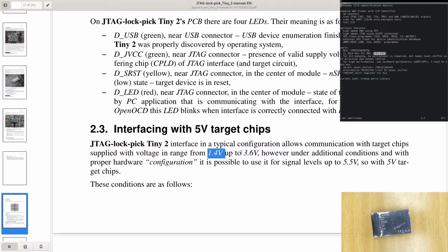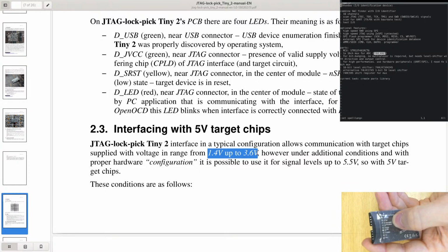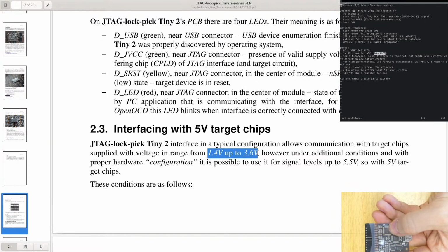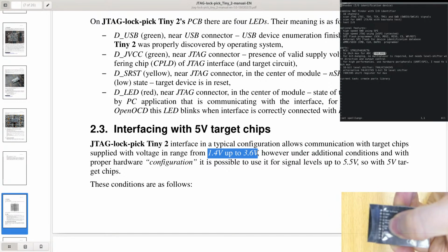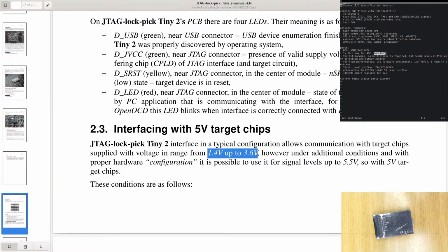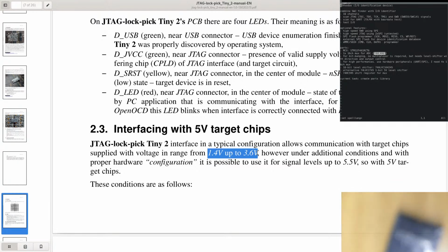This is why it uses the CPLD. This way it can route any pin of the FTDI to any other pin on the JTAG adapter, and you could reroute it actually. So here we have already a fixed pinout, but this CPLD is programmable. So you could actually reprogram it and have a different pinout, because this, yeah, this... those targets.